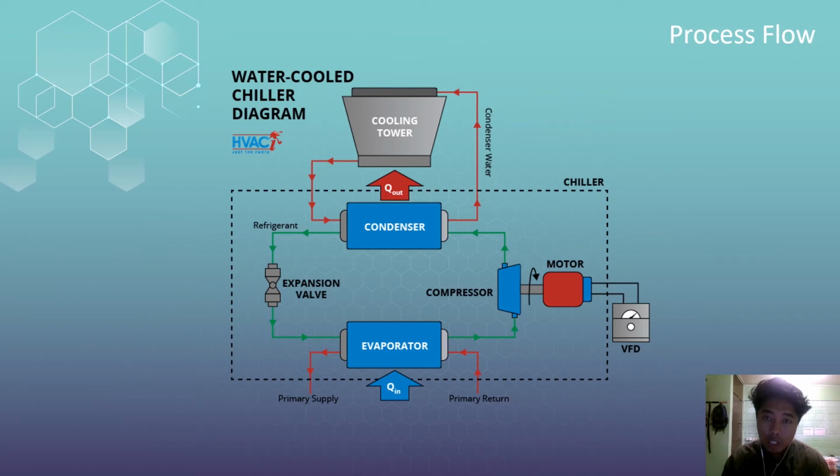To cool a building or process, the transferred heat must ultimately be rejected outdoors or to another system. The total amount of heat rejected includes the sum of evaporator load and compressor work, and the motor inefficiency. In a hermetic chiller, where the motor and compressor are in the same housing, these loads are all rejected